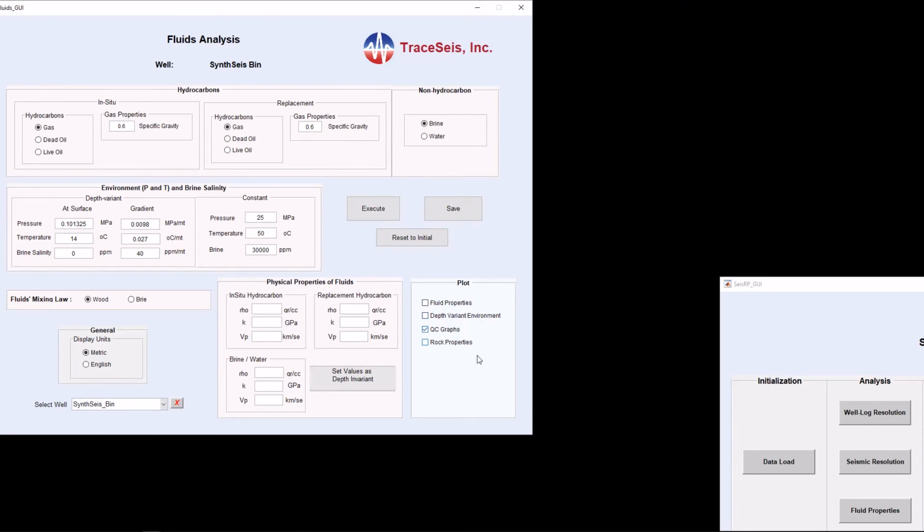The last checkbox in the plot box is the rock properties checkbox. When this is selected, we are prompted for a couple of parameters. SW is the water saturation to use in the fluid substitution. A value of -1 indicates the in situ water saturation. Matrix is the bulk modulus of the rock in which the water saturation is going to take place. That is where the target or pay flags are. This can be typed or selected as a lithology.